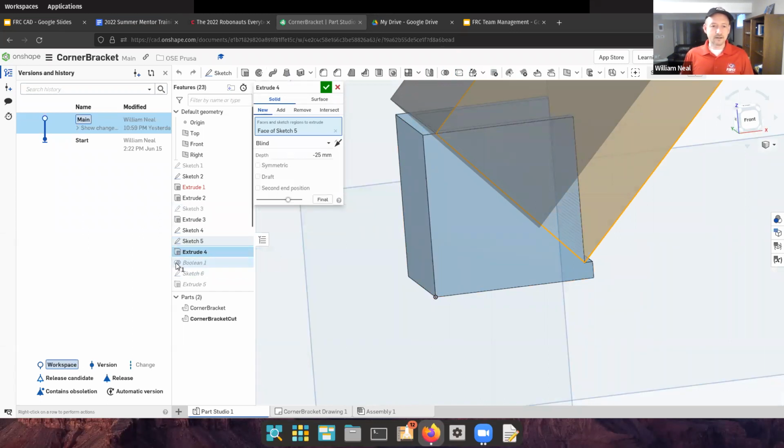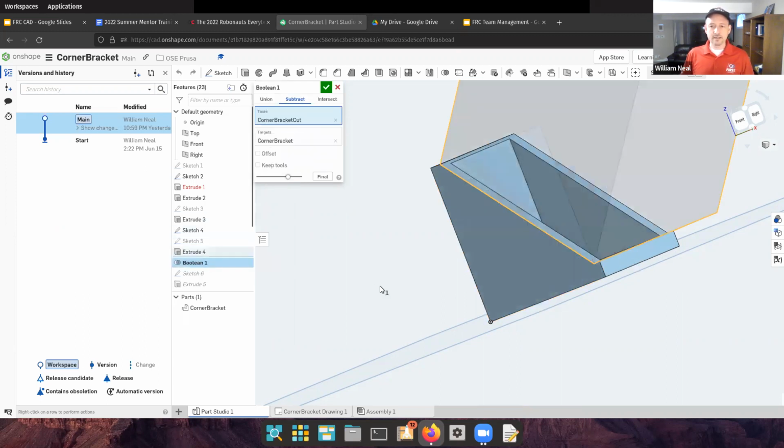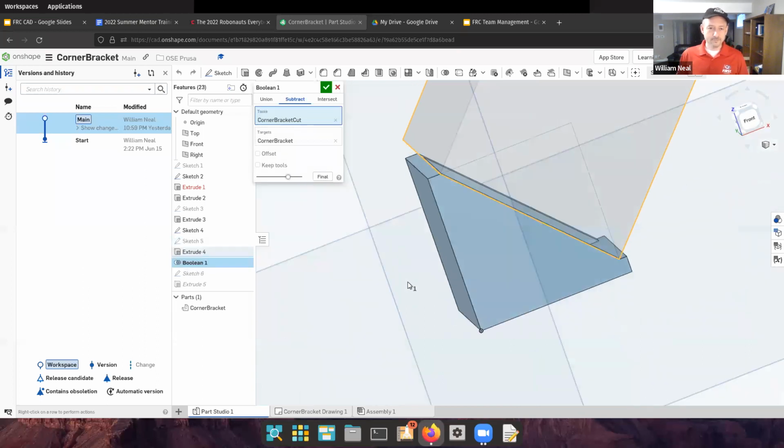And there you see there, I used a Boolean operation to cancel the parts of this one piece here, which is a rectangular region at an oblique angle, and take away the parts that are overlapping my main model. And so after the Boolean is applied, it cuts that out.